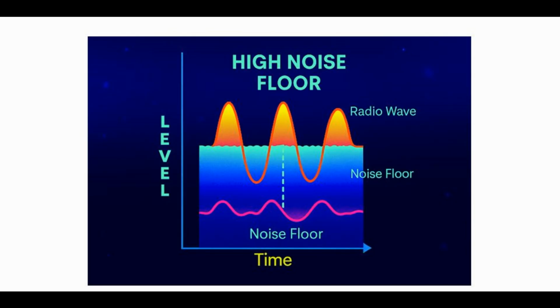When making comparisons between different modes of operation, the noise floor is an important part of the discussion. The noise floor is the level of background radio noise present in a receiver or in a particular radio environment. The noise floor is made up of natural and man-made noise sources. It is the baseline signal level, below which incoming signals cannot be distinguished. In other words, any signal weaker than the noise floor will be lost or become unreadable.